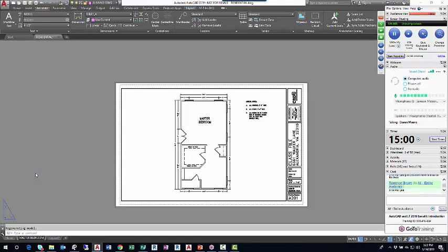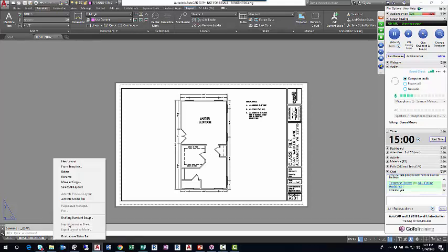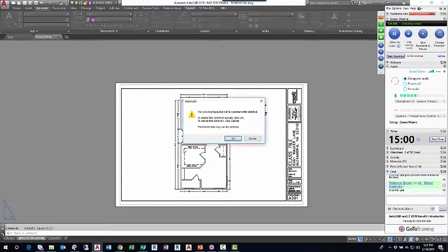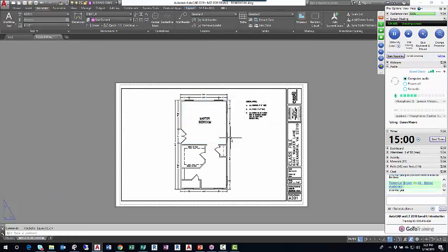That way when somebody looks at this PDF without even opening it, they know what it is. So it'll be residential master bedroom. I'll hit save on that. And if I'm not going to do a second layout, I could right click over layout 2 and delete that. If I don't need it, I'll just get rid of it. And I'll save the drawing.